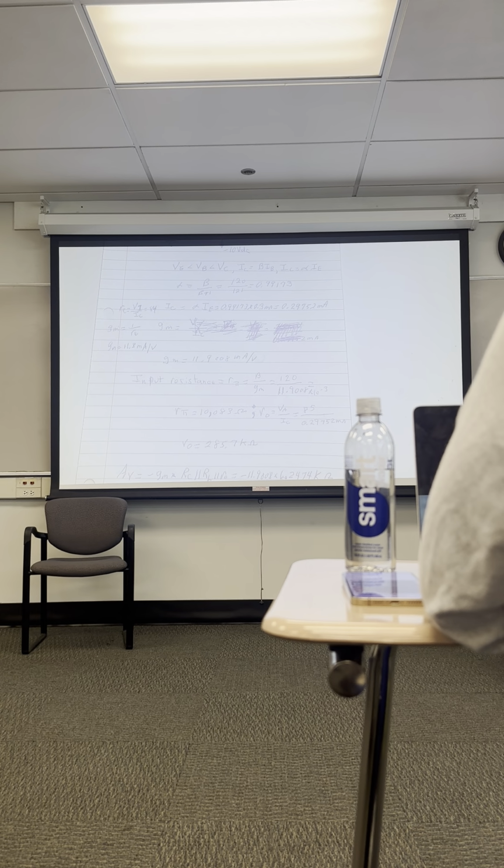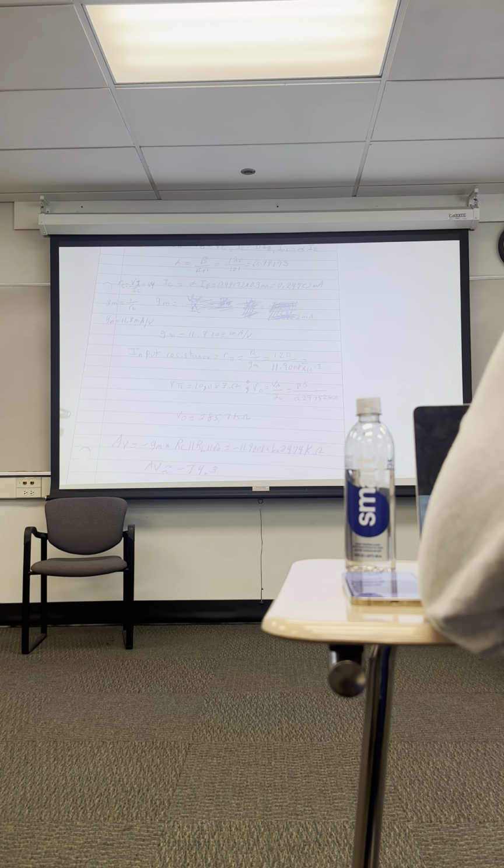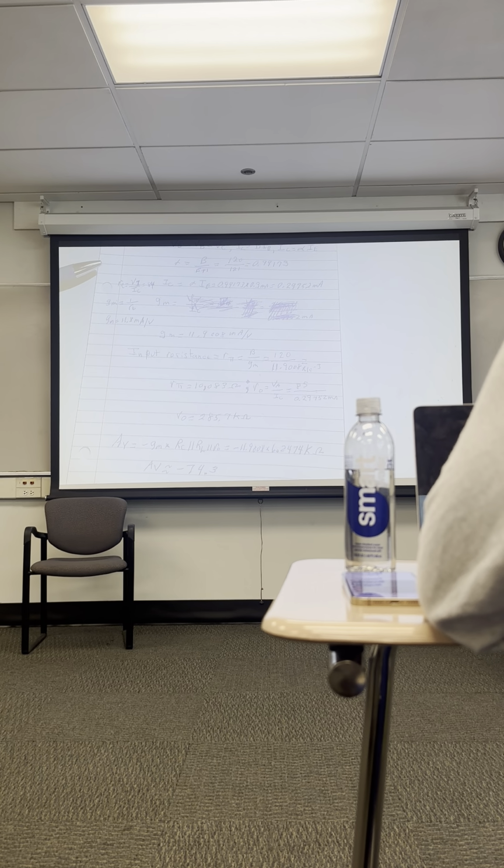And now we have all of the small signal parameters. The small signal parameter we need to solve this first part of the problem is G sub M. So A sub V is this equation here: A sub V is minus G sub M times R sub C in parallel with R sub L and in parallel with R sub O. I believe this number here is 6,247 ohms, or 6.24 k ohms.